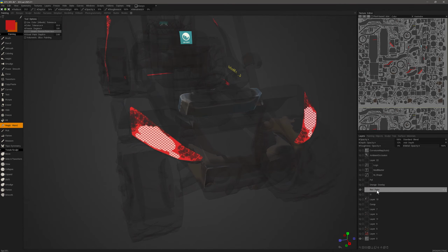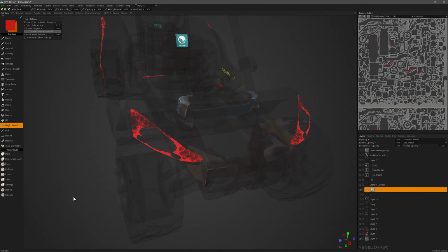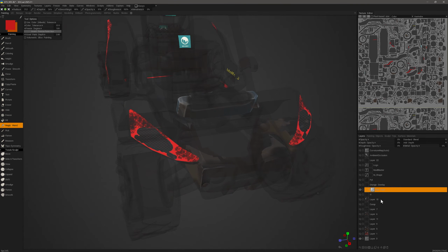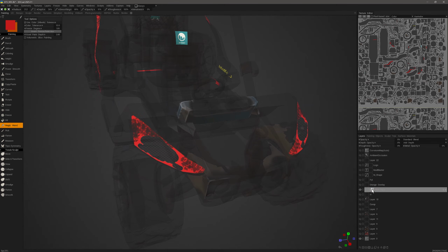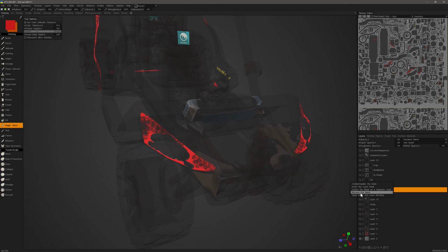If I want, I can now apply a layer mask with that freeze selection. Whatever I have frozen, 3D Coat will generate a layer mask from this. And this also works with vertex painting in the Sculpt workspace as well, just as a side note. But in this case, I don't need that masked out. I can just go ahead and remove the mask by right mouse button clicking.